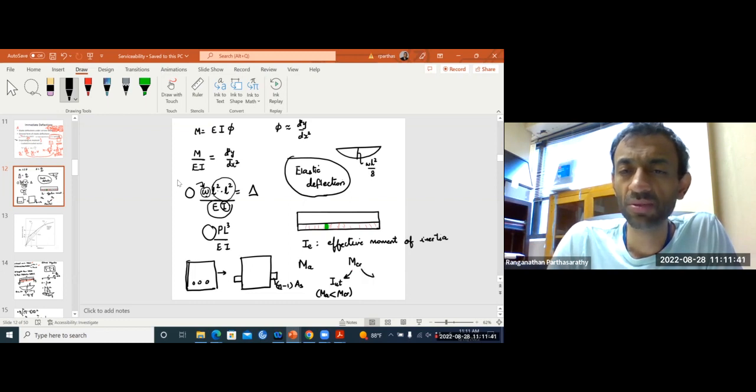Now, if your applied moment is more than cracking moment, then you are already cracked. So then you need to use the cracked moment of inertia, ICR. That is when MA is greater than MCR.